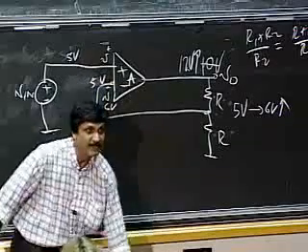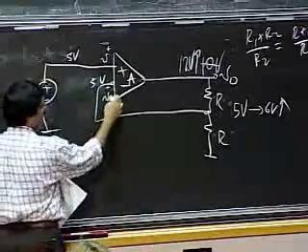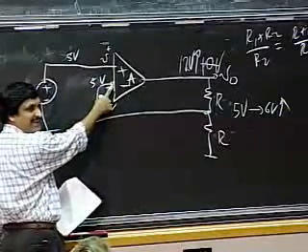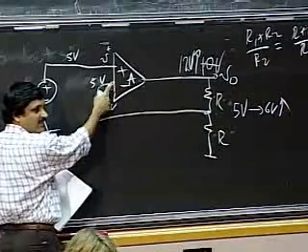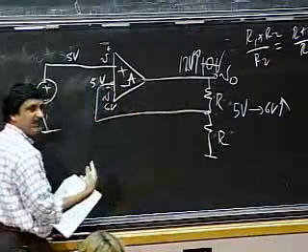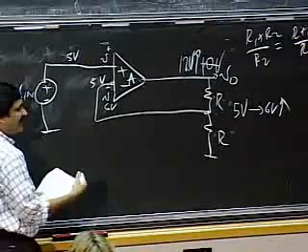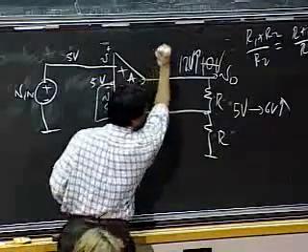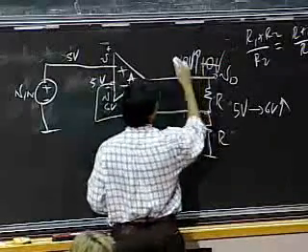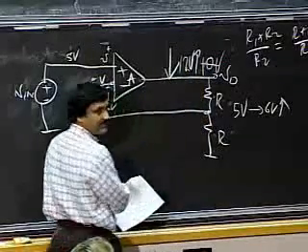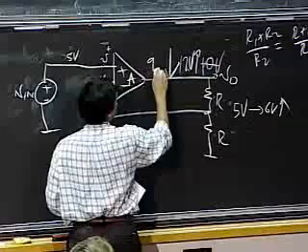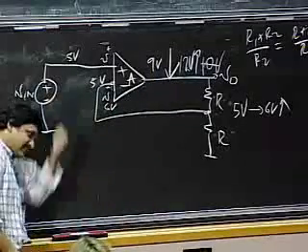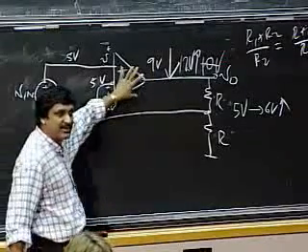Output should go down, because the voltage at the negative terminal is higher, and so the output is A times V plus minus V minus. And because this has gone down and this has gone up, it's going to try to pull the output down. So that's going to pull the output down, let's say to 9 volts or something. Ka-chunk. So there's a big battle going on here.